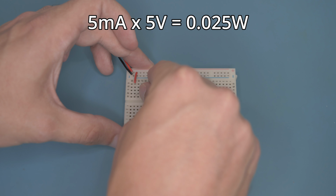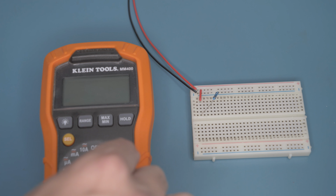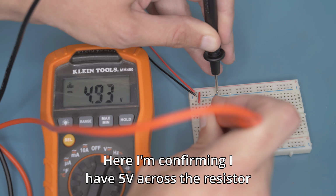5 milliamps times 5 volts equals 0.025 watts. Wattage is just the voltage and current multiplied together. These cheap resistors are rated for a quarter watt, so this is well within what they can handle.